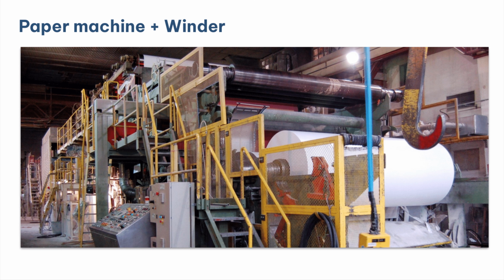A paper machine and a winder. Paper machines have been collected with portable walk-around systems for years, and it can get you plenty of actionable data. They do sometimes have very quick failure modes, especially if water is involved. So online systems are a great option for a paper machine. They can adapt to the changing speeds and states based on the grades of paper that you're running, and they can take in that data.